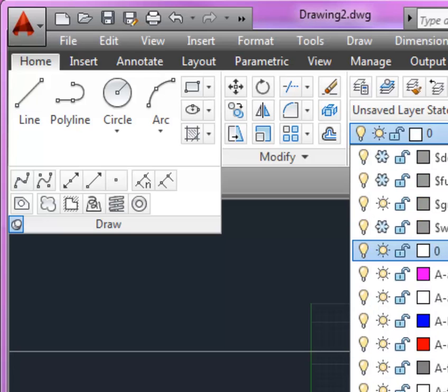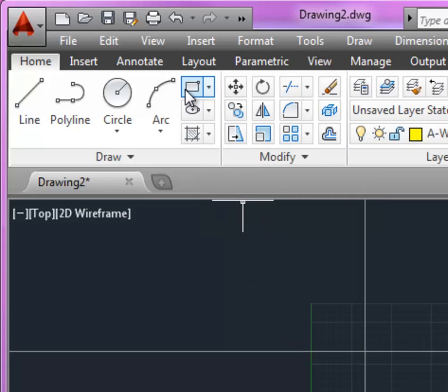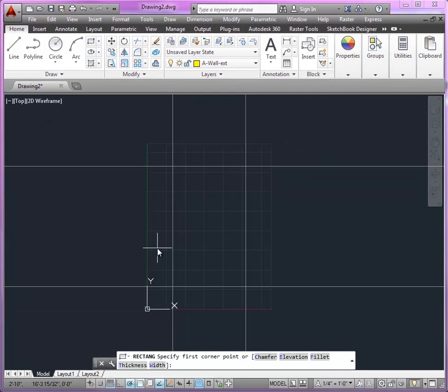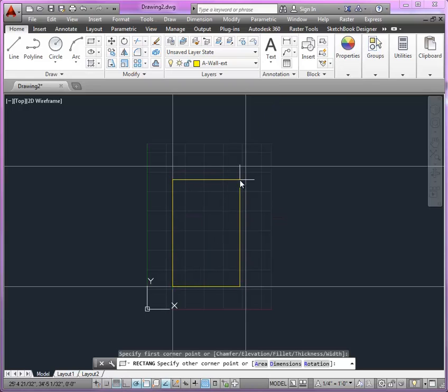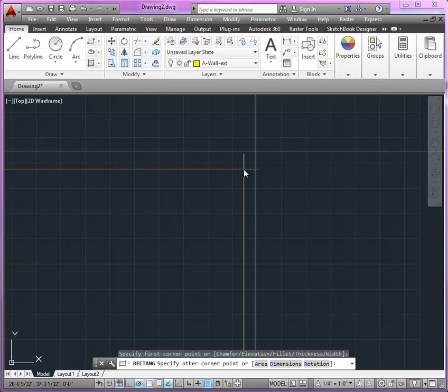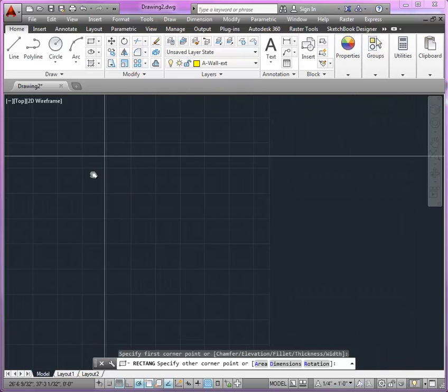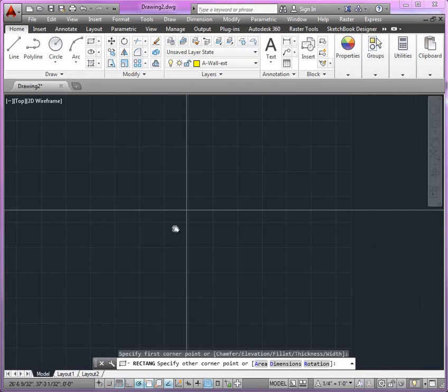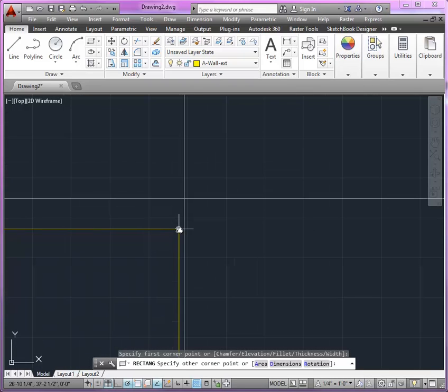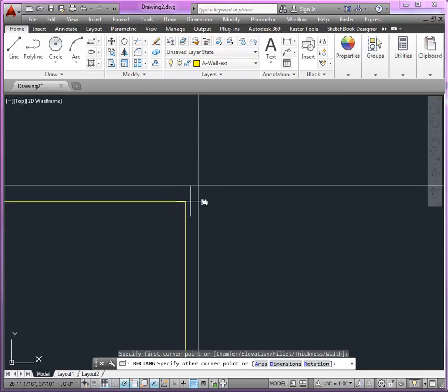We're going to go to the A-wall exterior layer, right? And I'm going to use the rectangle command. I can start with the rectangle command down here in this corner using midpoint. And then notice here too, if I use the middle button, the scroll wheel, just wherever you're pointing, roll forward. Don't push, just roll. If you push, that becomes pan. This is dynamic navigation. Push for pan. Roll back for zoom out, roll in for zoom in. You're going to use these quite a bit, all right? Because you don't want to accidentally snap to the wrong point. You want to see it clearly.